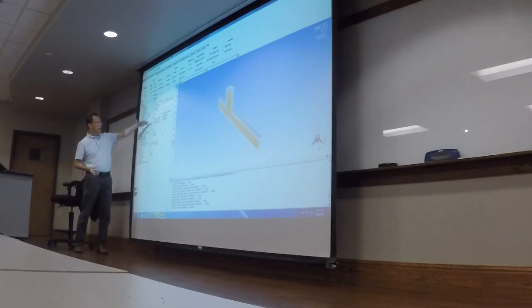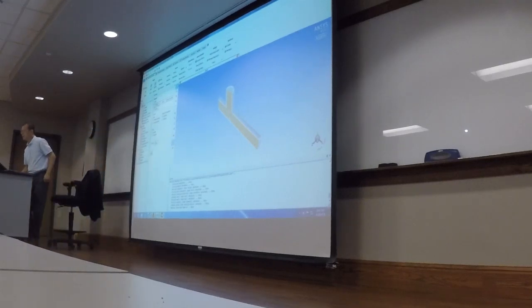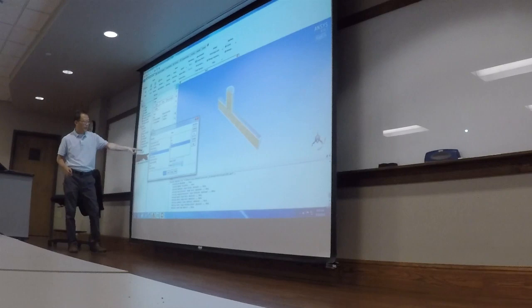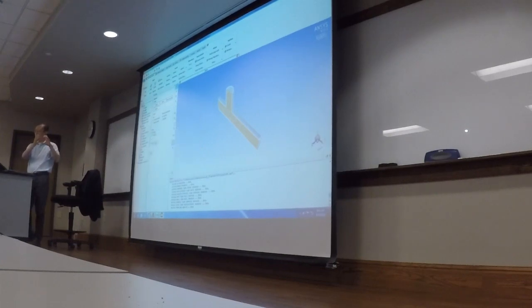Just like the tutorial, let's go down all the steps. Our geometry is important. All right, so here, pressure based, keep that, absolute, steady state. Units, lengths, inch, close. Fluent will understand we have a 2-inch pipe instead of a 2-meter pipe. It's a 2-inch pipe. That's all we want to do for general, and let's go to models.